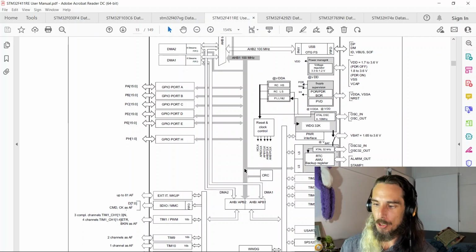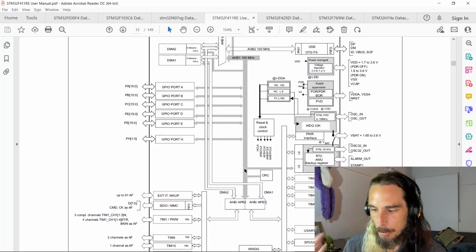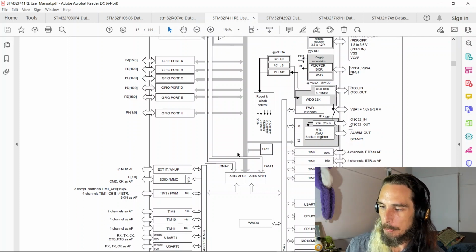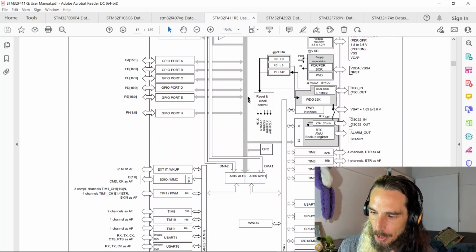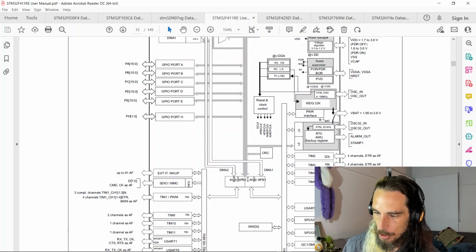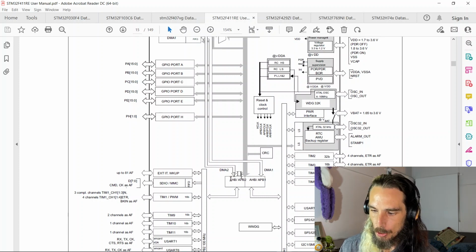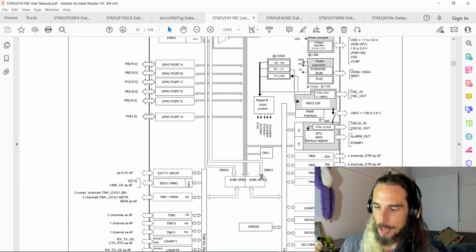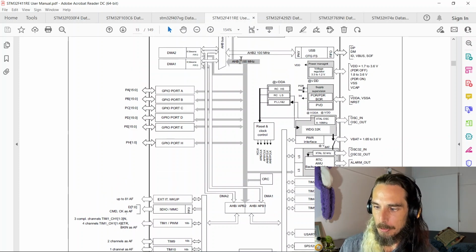So I'm going to refer to them as the host buses and the peripheral buses because it's going to make it a little bit easier. It's the typical lingo I prefer to use. So our host bus is the one in grey. We've also got 2 other connections to these bridges. DMA2 is connecting to peripheral bus 2, and DMA1 is connecting to peripheral bus 1. That allows the DMAs to be able to access those peripheral buses without tying up the host bus, essentially.